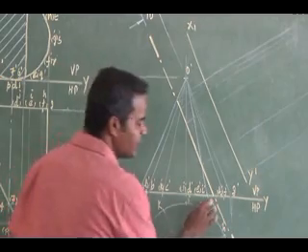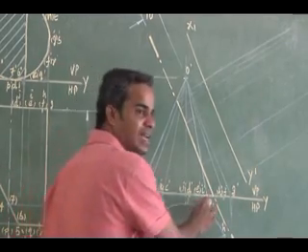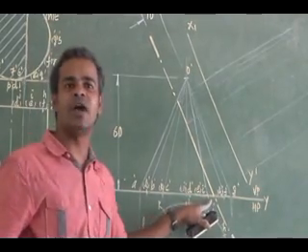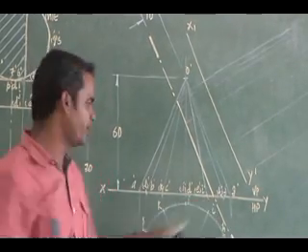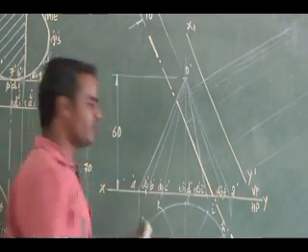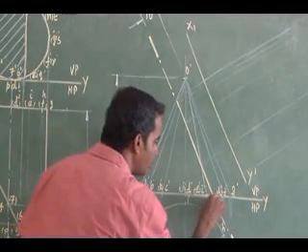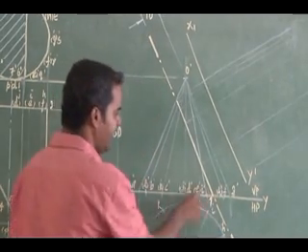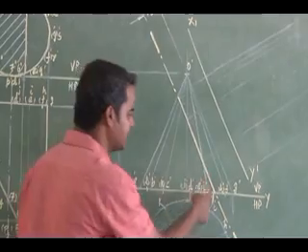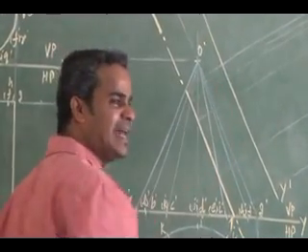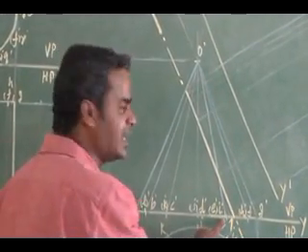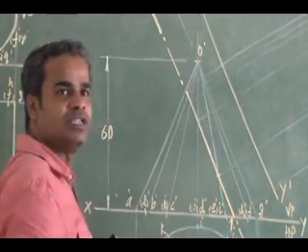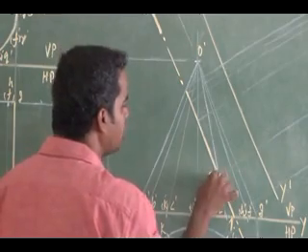See here, I am giving the cutting point 1. So the cutting plane cuts the base of the cone. So how many cutting points on the base will I get? Two cutting points. One is visible, one is hidden. So first of all I am giving the visible cutting point 1 on the base. Right. Then you move along the cutting plane, searching for the visible generator it cuts. Visible generator here is IO. Wherever it intersects the IO generator, that is my cutting point 2.